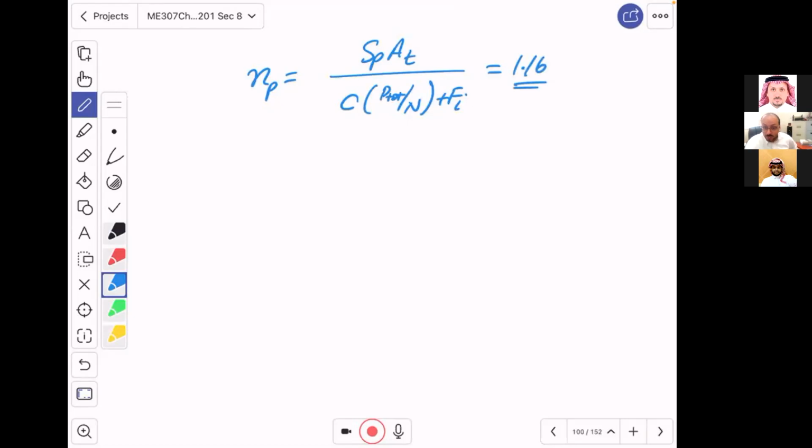And this is something we told you about. We told you that the proof factor, this yield factor, which is based on proof strength, will not give you a far limit from 1 because the load is going to push the stress in the bolt near the proof strength.